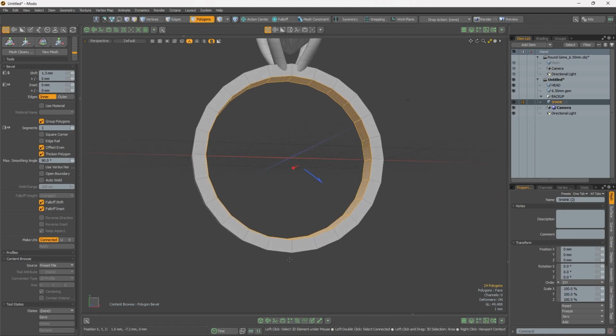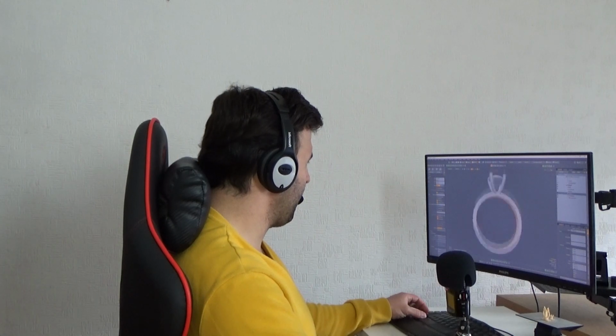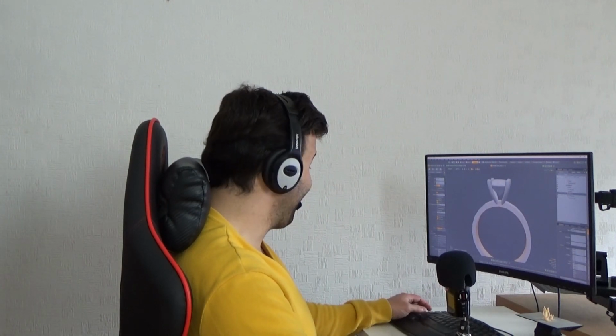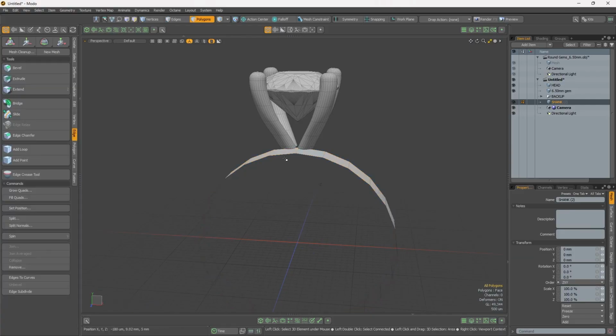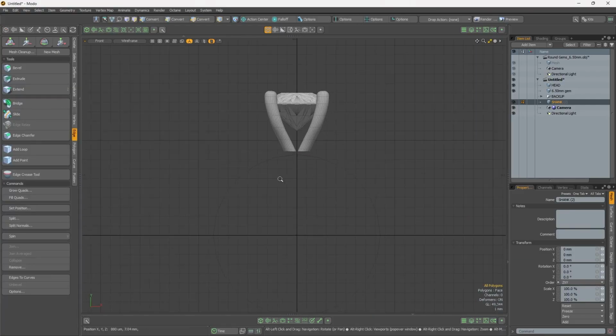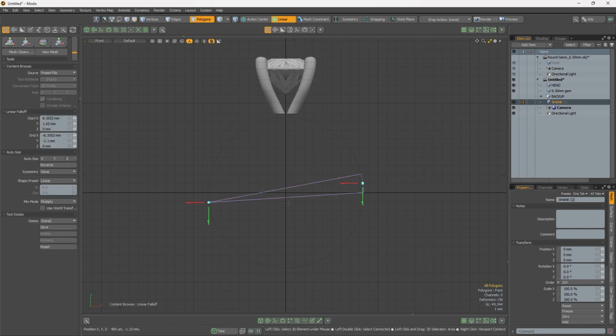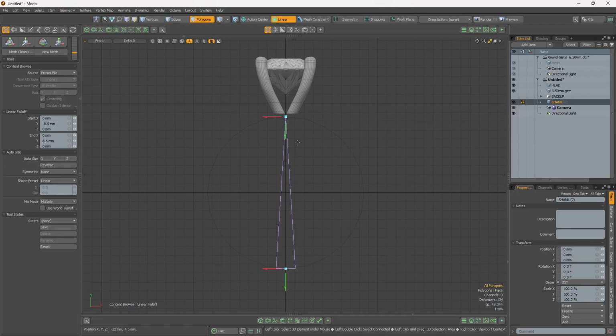At the bottom, I want to have a little thicker, up to 1.8, and at top something about 1.3, 1.2 in CAD, like in 3D software. The reason I say in CAD is because in the manufacturing process you lose some thickness, so it's better to keep in mind when you design in 3D.